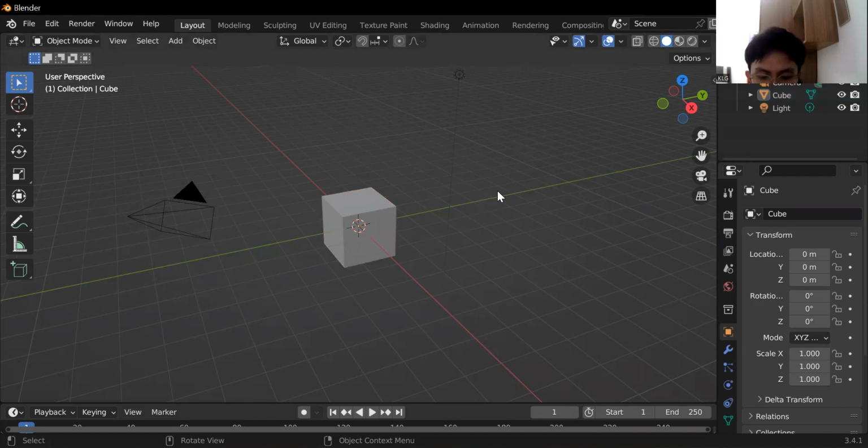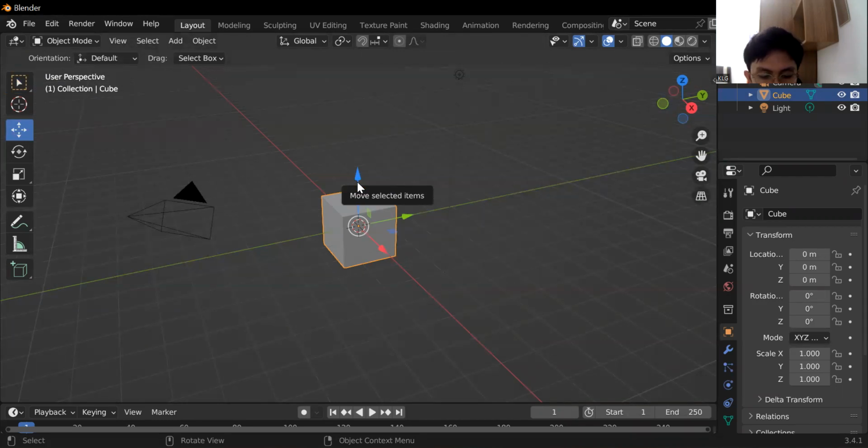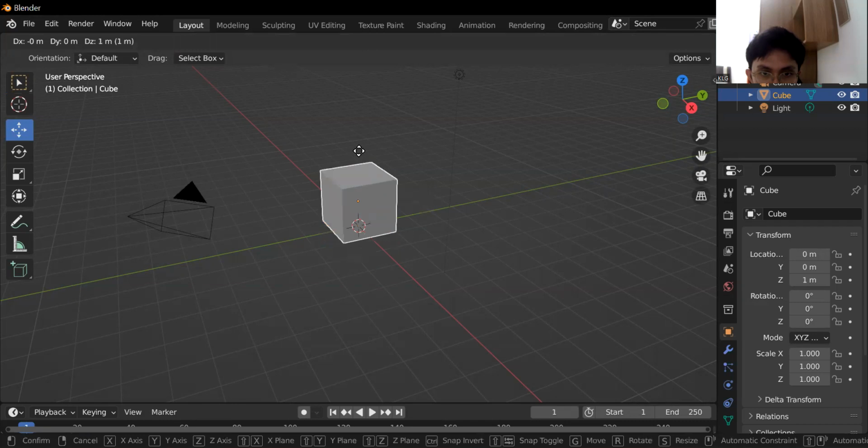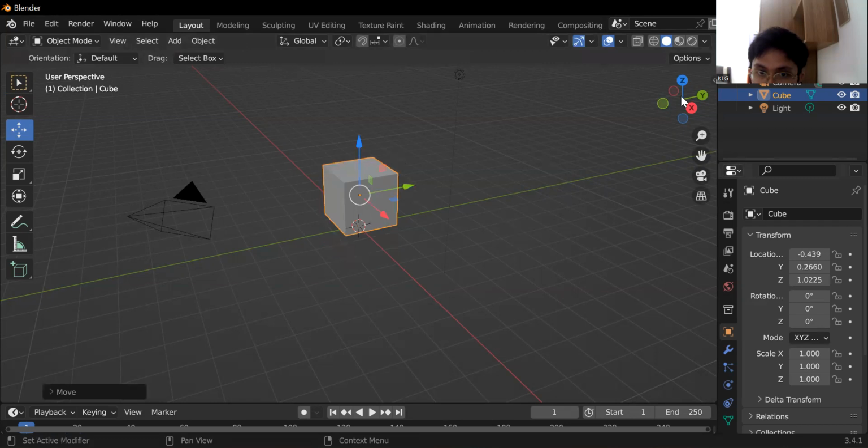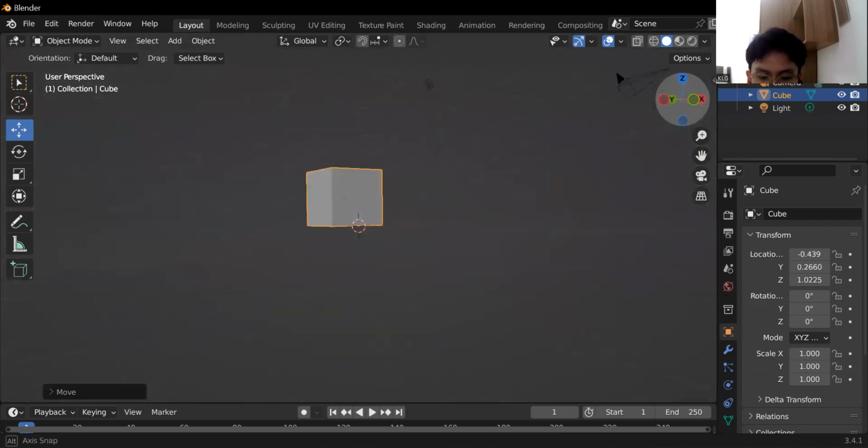Hello everyone, in this video I will explain how to set my object to look like wood. So I use this cube object before I do shading. I will raise this object by selecting it, clicking move, clicking the Z axis, and then holding the Control button and dragging it up like this, so that it will be above the surface.